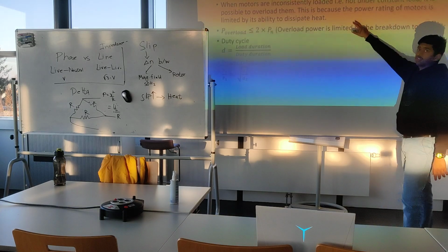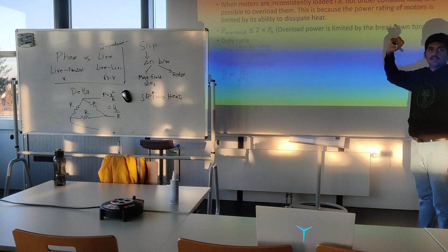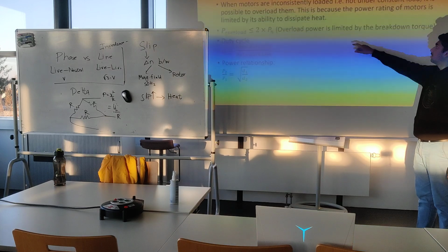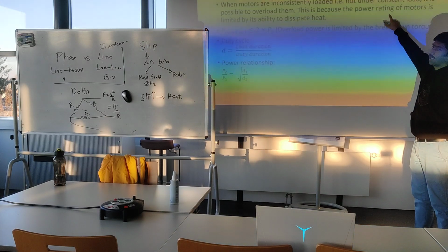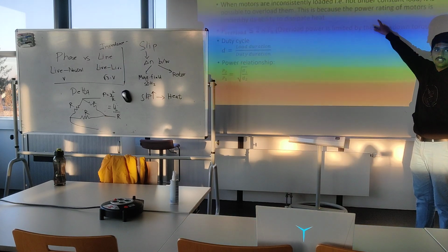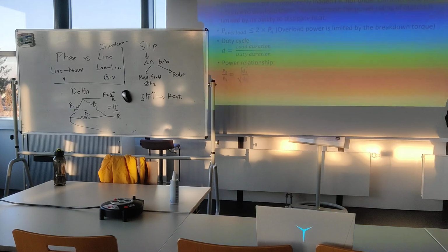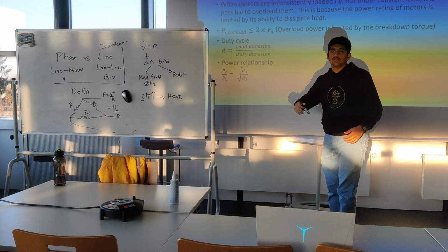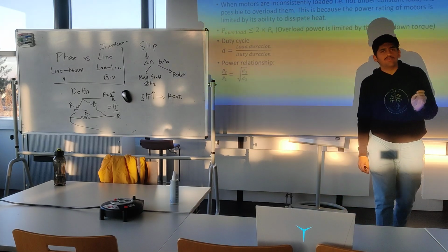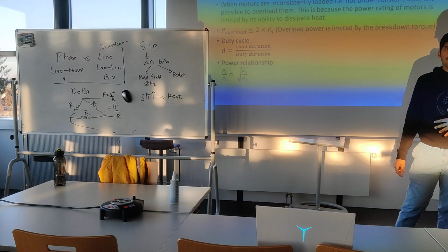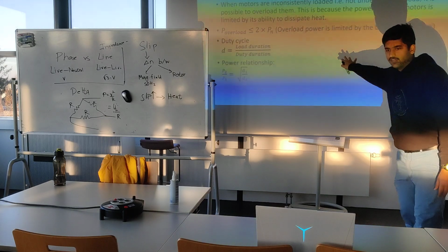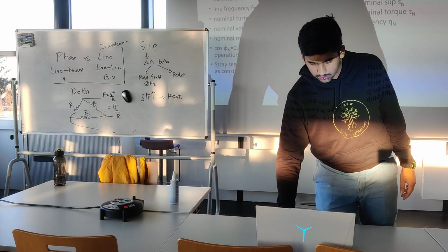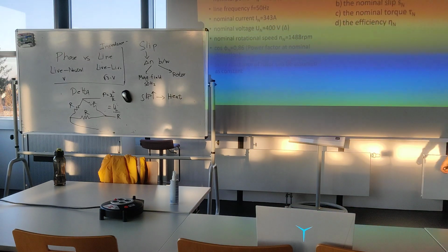Like I said, it is possible to overload a motor. You can take it to the breakdown torque level, but the problem is that the heat produced is too much and you're not able to dissipate it over a long time. So this is why we use duty cycles, where you take it to high loads for short periods of time and then back to low load again. But we will discuss duty cycles later. So here we have a simple question. Let's start.